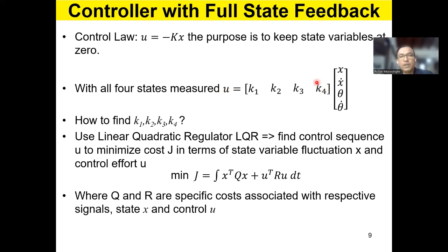And these 4 gains are found in MATLAB using the LQR command, right? For that, you need to refer to the notes from 2 weeks back and MATLAB codes on the linear quadratic regulator. So here, just to mention what it does, it optimizes a certain function, an objective function, let's say cost in this control. So you start the pendulum with a certain angle and the linear quadratic regulator will stabilize it and move the cart to the desired position.